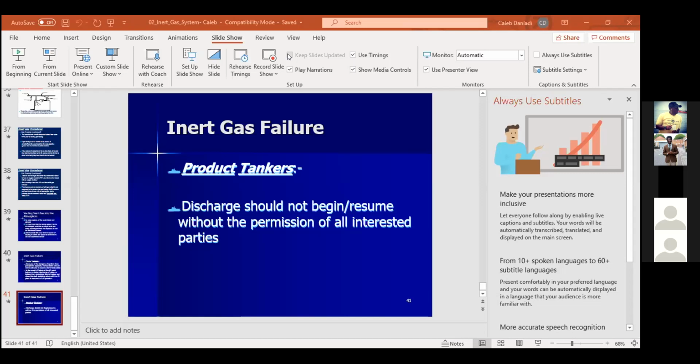Inert gas is a safety requirement on the ship. If you check in SOLAS, inert gas is among the fixed firefighting equipment, a requirement. But for small bunker barges and small tankers, less than 20,000 deadweight, except you have 8,000 deadweight tons and you have low flashpoint cargo that requires inert gas, in such a case you don't require an inert gas system.